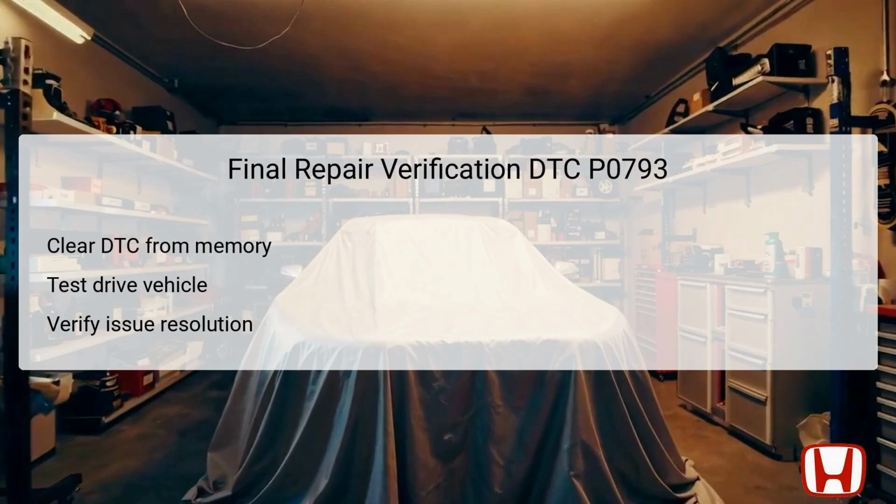After completing the troubleshooting process and executing necessary repairs, it's critical to verify the resolution of DTC P0793. This involves clearing the DTC from the vehicle's memory using a diagnostic tool, ensuring that any previous error codes no longer affect performance assessments. Following this step, a test drive of the vehicle should be conducted under conditions that originally triggered the code.